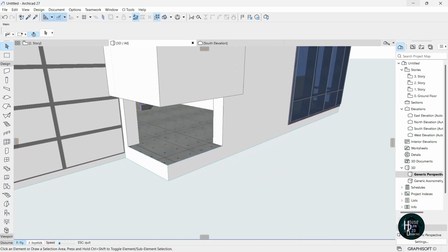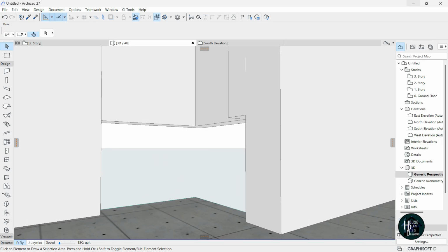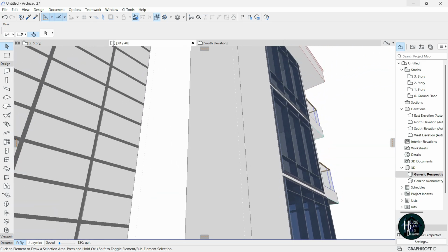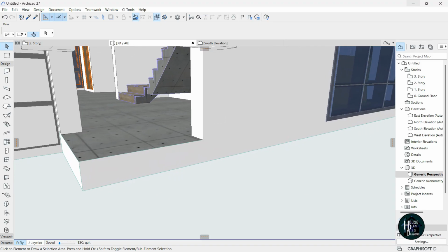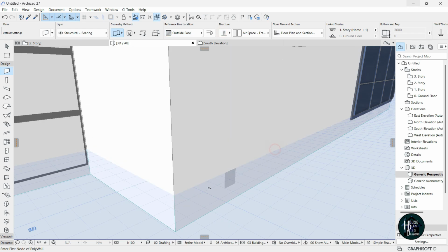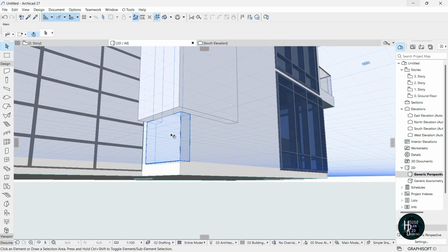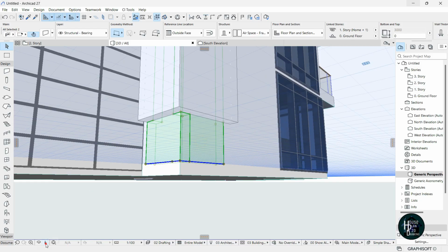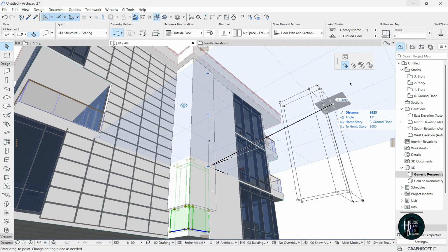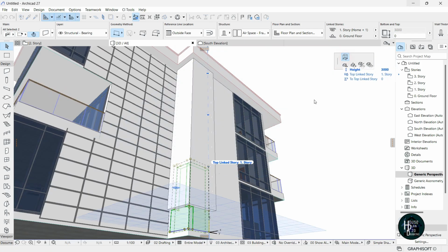Okay, now concerning this side here, we're going to try and adjust this. Okay, because this needs to be adjusted properly. So what we want to do is to just hold on Alt, select on this wall, click this node here and make sure I'm selecting the other surface, click this and double click this side. Okay, hold on Shift, click this. Okay, and now click on this node that I have seen on that side, click on this stretch height and move it downwards to this side.